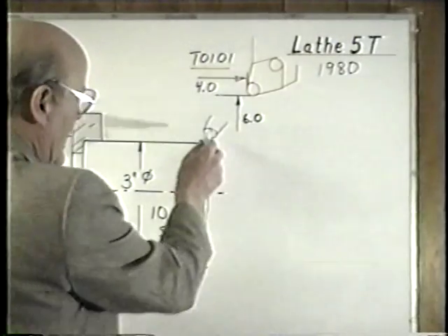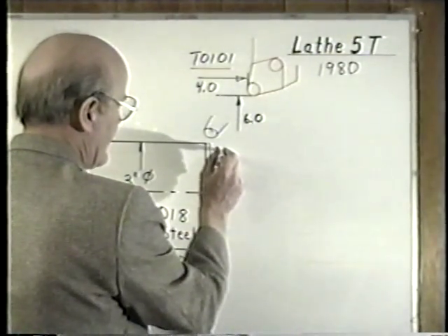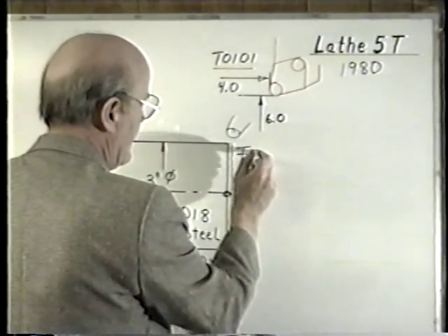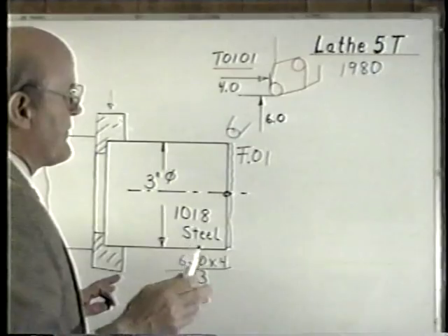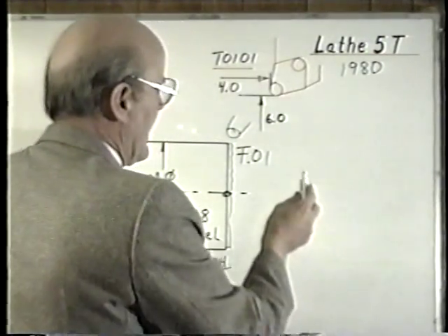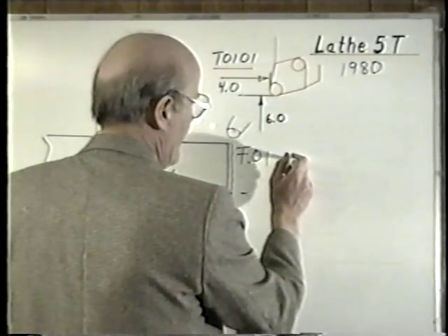The feed rate across here, let's say I feed somewhere around 10 thousandths, it would look something like this. This is my F value, 0.01. But there'll be some differences here. I really can't write it down like this. Our typical program would look something like this. Then in our first line, in line number 1,